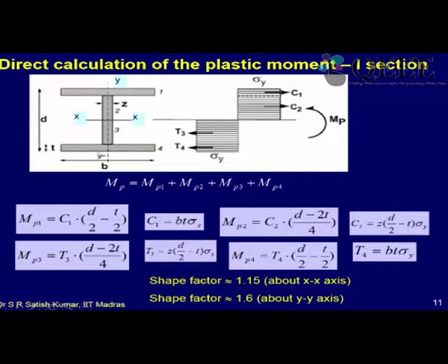and that into lever arm, plus the CG of this area, will give you the lever arm, into area into Fy, which will be the C or T value. So that will be the MP. But that's a cumbersome procedure, because again you have to find the CG of a complicated shape. So it's easier to rather divide this into 4 rectangles.